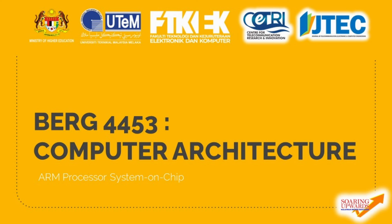Manufacturers can customize ARM-based chips by integrating different components according to their requirements. For example, a smartphone SoC might include a CPU, GPU, modem, and image signal processor, while a microcontroller SoC might include just the CPU and memory controllers. ARM SoCs also excel in terms of power efficiency. Thanks to their RISC architecture and advanced power management techniques, ARM processors can deliver excellent performance per watt, making them well-suited for battery-powered devices where energy efficiency is critical.